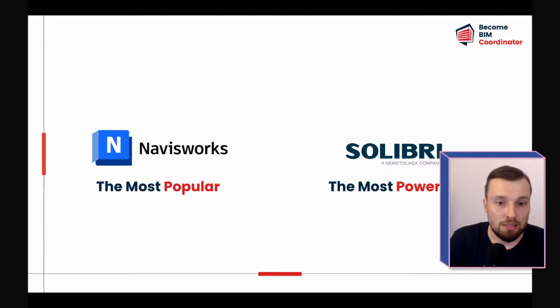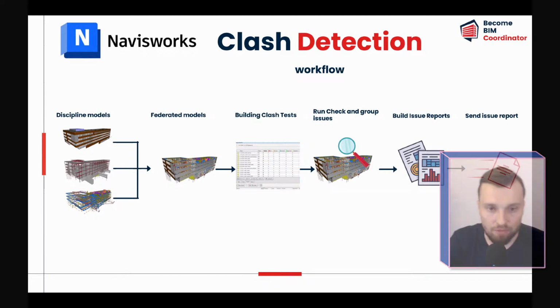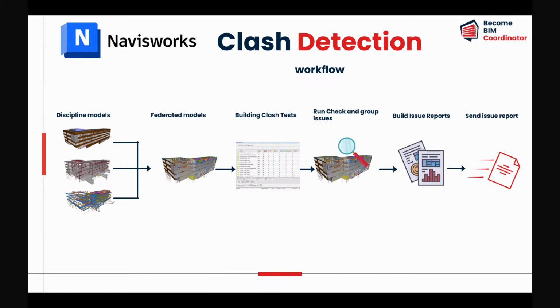Before we dive into Navisworks to show you the demo, to help us understand how the Navisworks checking process works, I created a quite simple diagram. First, before we check anything, we need to receive disciplinary models from the teams. Me as a BIM coordinator, I need to receive a model from architectural, and installation has their own model, which they need to send to me. I combine these models into one single federated model.